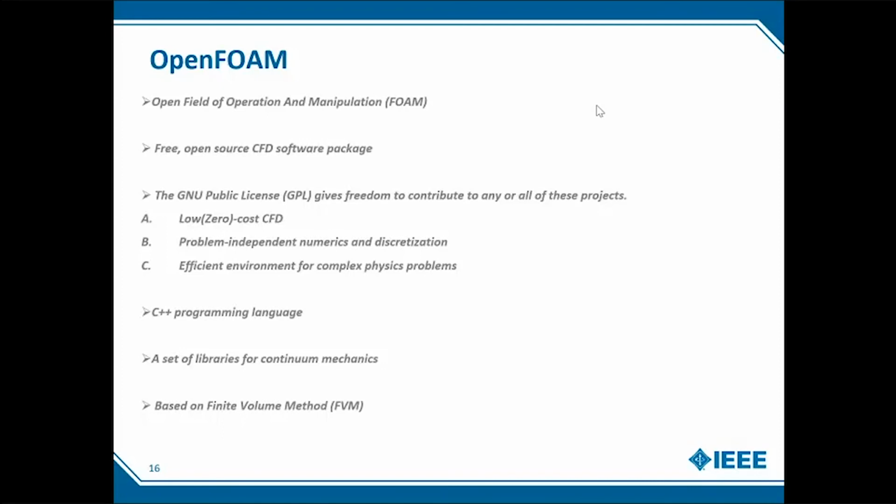You can get it at no cost, and OpenFOAM has a lot of numerical schemes available. Basically it's based on the finite volume method which I just described, and it uses continuum mechanics. So when we go to very small length scales, smaller than micrometer dimensions, for example microfluidics, we cannot assume continuum mechanics.